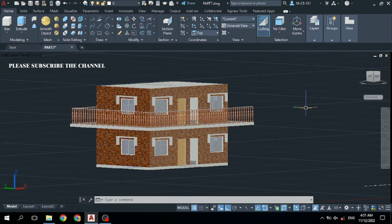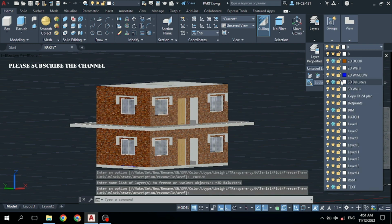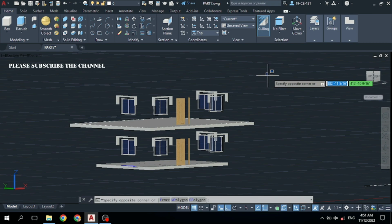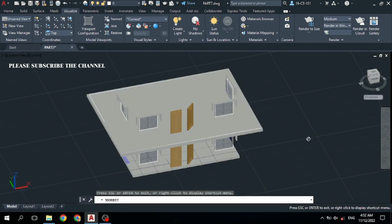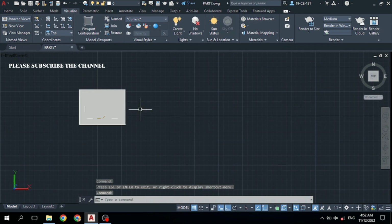So to draw the stairs, first of all I would like to unvisible this 3D wall layers and this balusters. Then it will be easy to work, and my computer will be less load. So for that, unvisible this 3D balusters and also this 3D wall. And after that, click visualize and select this top view, and also click at this top, and now draw here your stairs.